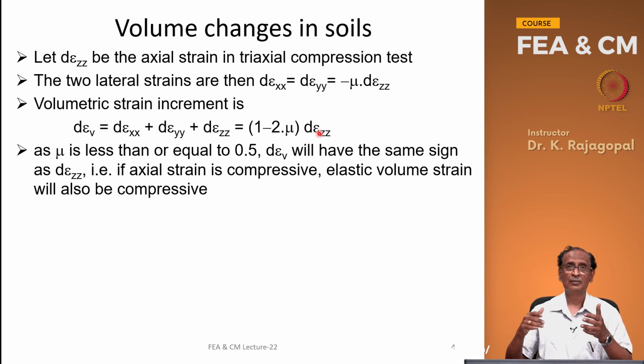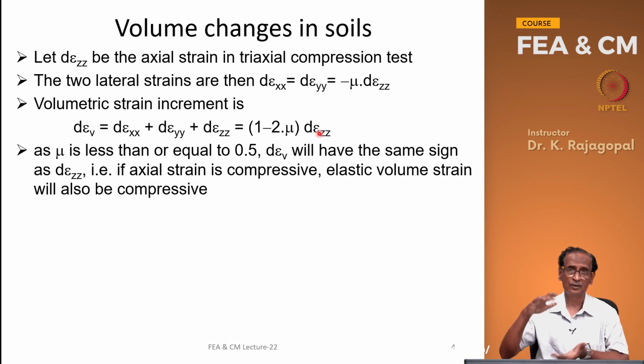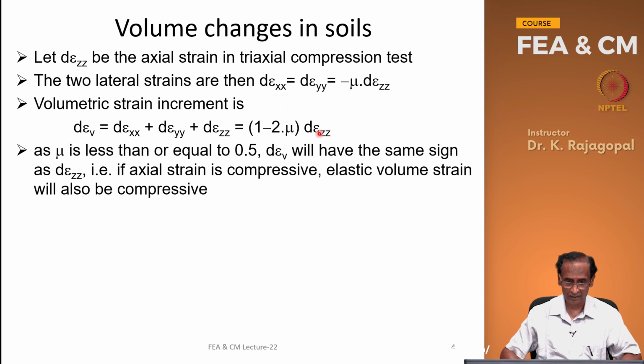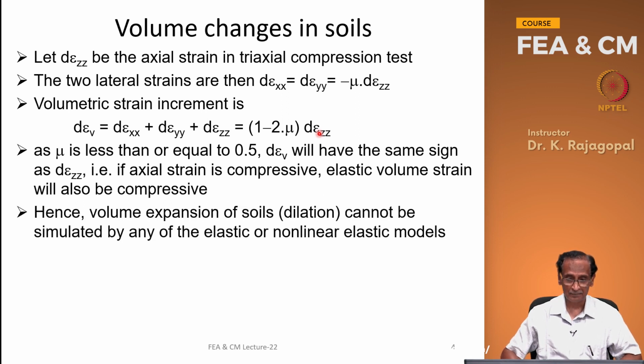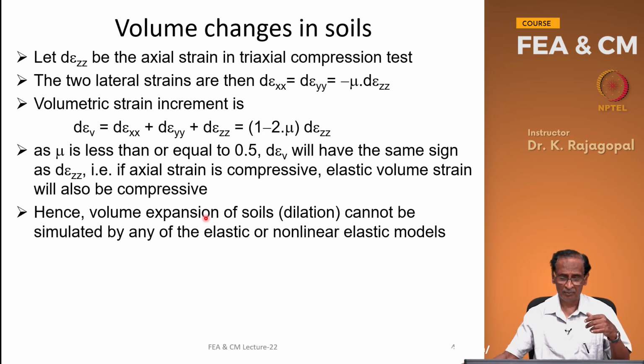So, we can say that all our elastic volume changes are only going to be compressive as long as you apply some compressive stresses. And on the soil particles, we cannot anyway directly apply any normal tensile strain. We can apply shear strain, but we cannot apply any tensile strain. We can apply compressive strain or compressive stresses. So, our dilation induced volume expansion we cannot model through any of our elastic or nonlinear elastic models, because